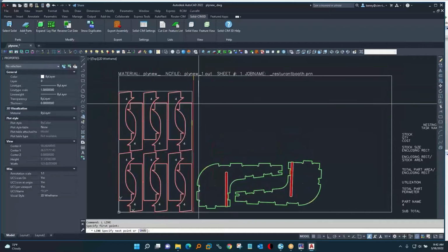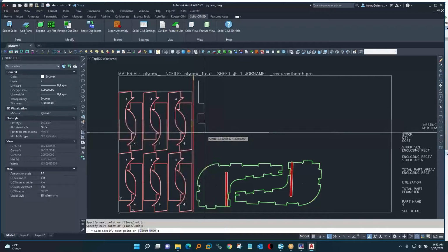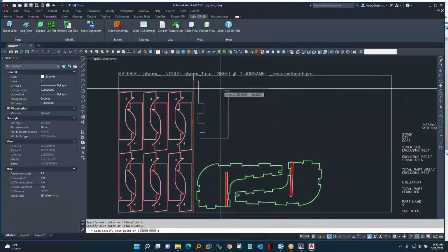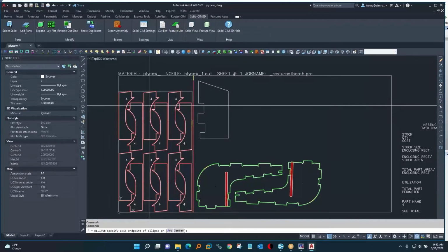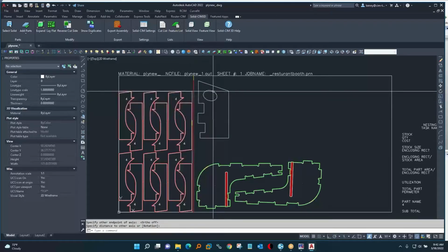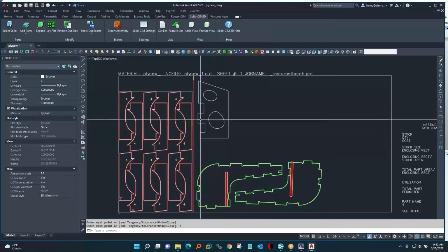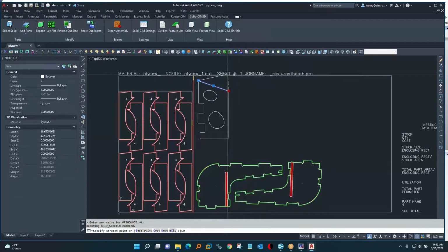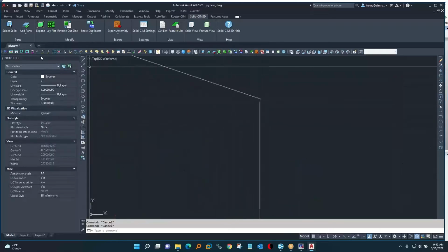Nobody has a better drawing program than AutoCAD. So if you're going to draw in 2D, compare that to any other CAM program that has lines and arcs commands. Okay, AutoCAD does it a little better and easier. Also, if we have ellipses and splines, I like to show those. We'll convert those into arc segments, where a lot of other programs will make a series of little line segments there. So we could take that, even if there's a problem in the drawing, because a lot of times if you get drawings from someone else, they draw sloppy, and there's a little break in the geometry there.